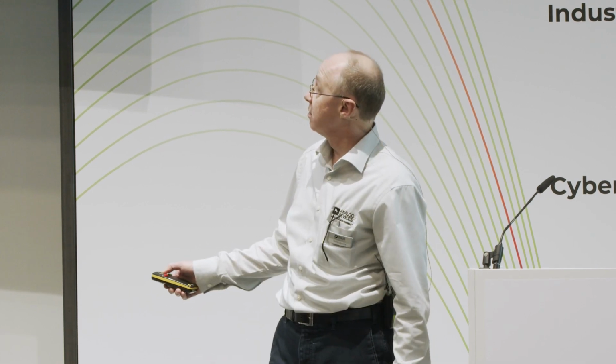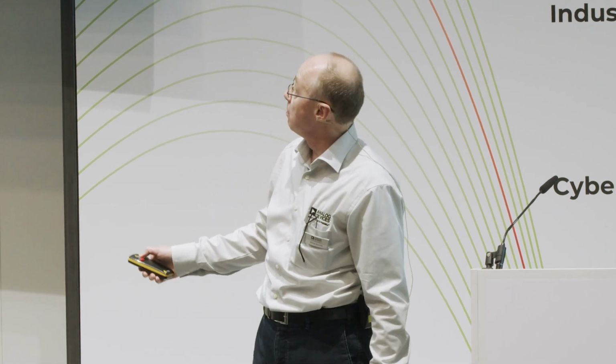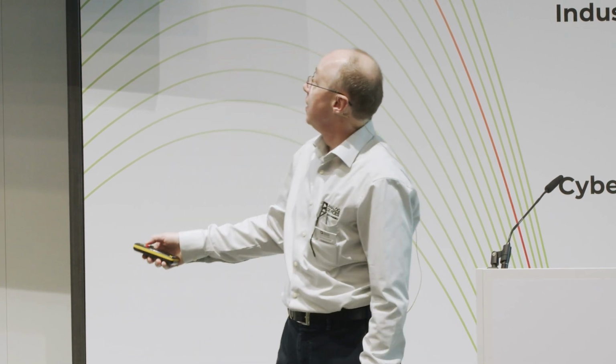So the principle is very simple. The challenge comes with scale. Even if I look at my own plant, we have a manufacturing facility in Analog Devices, and if I look at our own fab, there are hundreds and thousands of these nodes. They go through some field junction boxes. There is a piece of equipment somewhere, so the wires and cables from individual devices are congregated into some junction box, and then go through multi-pair, multi-core shielded cable. The cables are quite thick, with lots and lots of wires inside, and land up in a marshalling cabinet. Just to paint the picture, the marshalling cabinets in our factory are huge cabinets, and there are thousands of cables landing there.